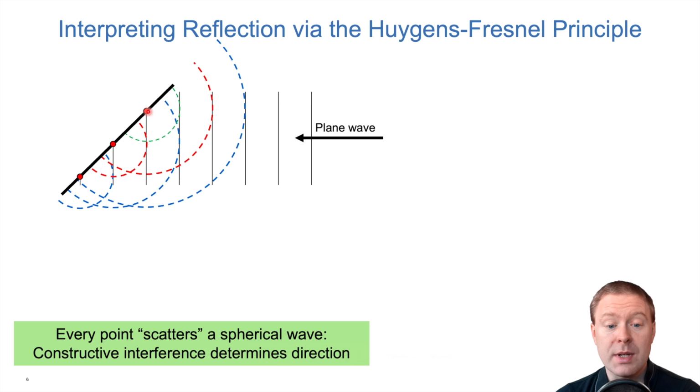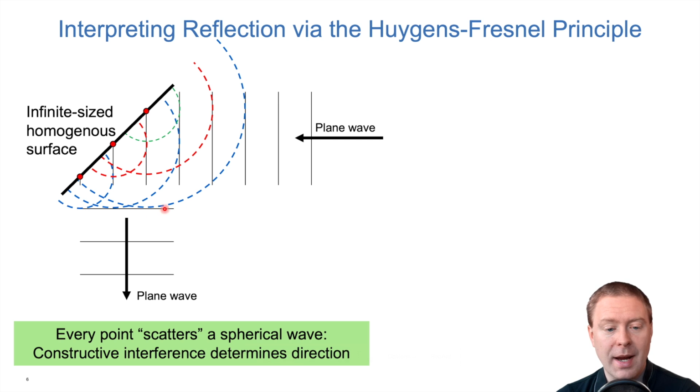So since the signal is reaching this point first, its reflected signals, these waves here, will have reached further away before the signal from here is being reflected. We have these two waves here, and then this one had not reached that far. But the blue curve here that is representing a signal that have traveled equally far, you can see that it is in this direction here where we will have a strong signal. The constructive interference will happen downwards here.